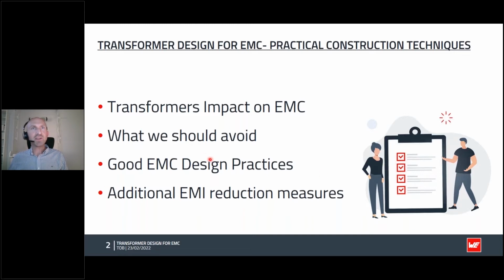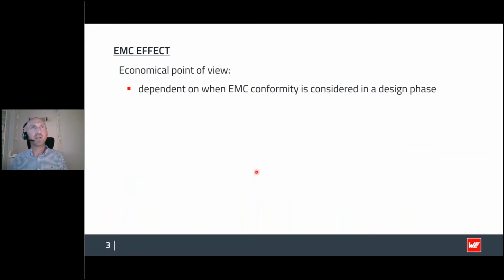So magnetic components are at the heart of every power supply, and when we also need to have isolation between the primary and secondary, then we need a transformer. And so the transformer is a vital part of every power supply and a vital part of isolation. But it also brings about some potential problems and some difficulties that can be had with EMC, and maybe people are not so aware of all the different measures that we can implement in the transformer just to help impact or help limit any impacts.